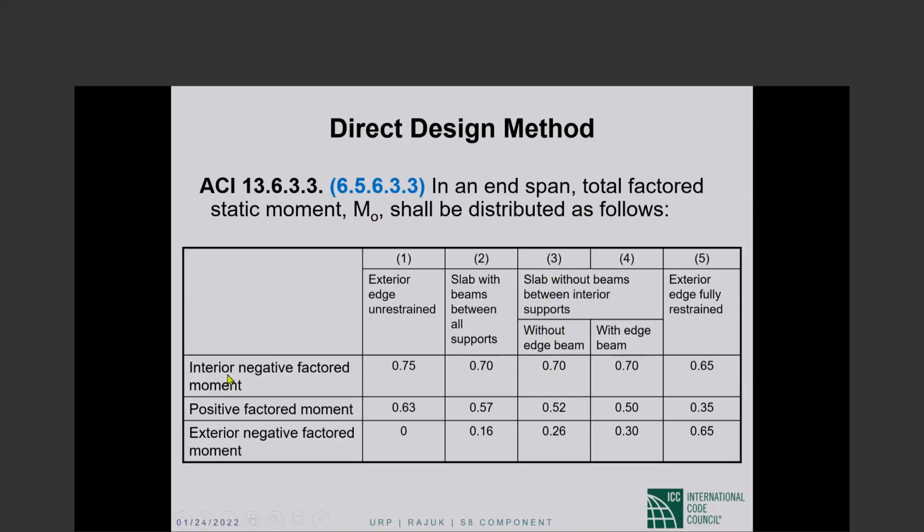this is an end span. The negative factored moment at the interior support is 70% of m sub 0. The span moment is 52% of m sub 0.